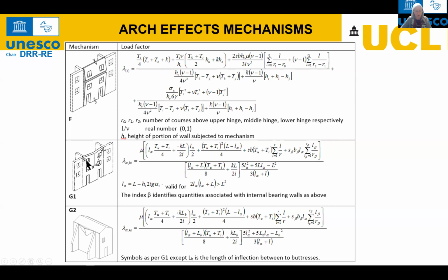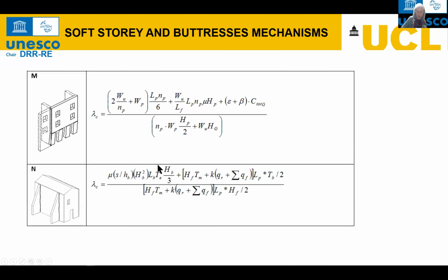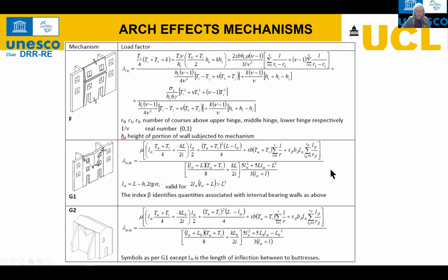Here, the unknown is the diagonal line, which will depend both on the ratio of height to width, but also on the type of fabric. And again, the size of the brickwork and the masonry is very important, but it will also depend on the distribution of the loading conditions on the walls or on the side walls. Here, for instance, you can also notice that we use different levels of thickness. So also the importance of determining the thickness between the top and the bottom becomes extremely relevant.